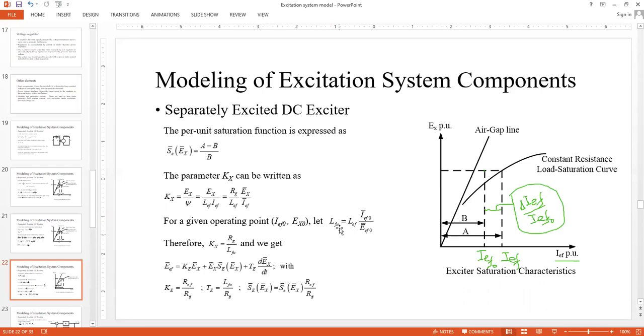So why is it actually changing? Because you see the field inductance is actually a function of the field flux linkage. Okay. So because your flux value is actually a function of current, number one. Second thing, this distance is actually increasing even before saturation. Even before saturation, this distance is increasing. The complete saturation occurs probably somewhere here. So this gap is actually changing depending on your operating point selection. So that's why the unsaturated field coil inductance is also a function of this operating point itself.